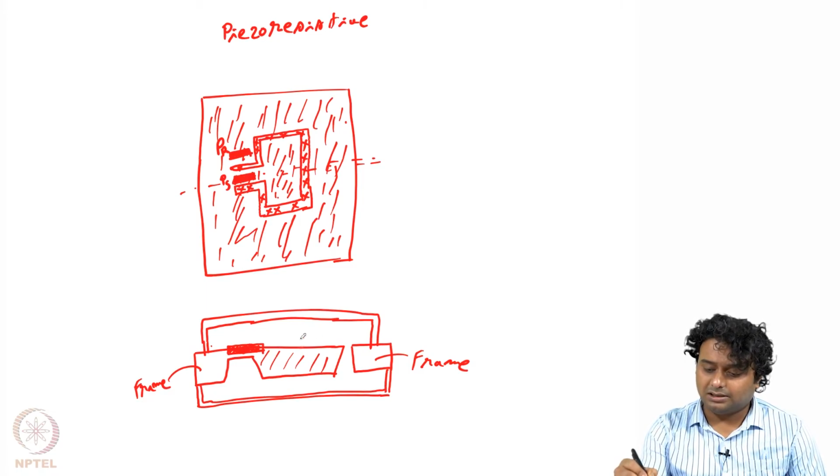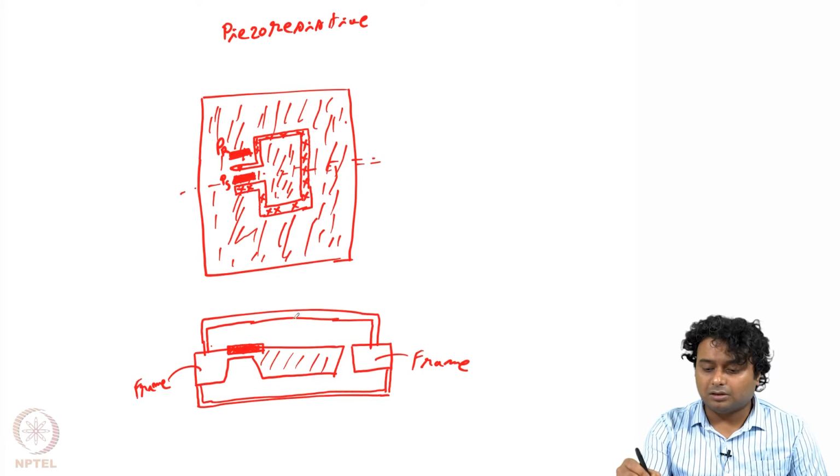As it is moving, to get rid of stiction or any in-use stiction kind of effect, what we can put in the top cap or bottom cap is this kind of dimples or anti-stiction tips. So even though it moves top and bottom, it will not get stuck to the top cap or to the bottom cap.